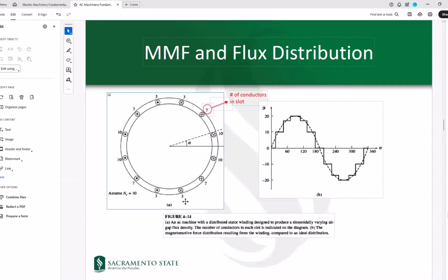But that is not as simple as that. You really have to have a specific setup to make that pattern in a sinusoidal way, if that makes sense. So this is just something to note. So this was only for phase A, and now for phases B and C, you can imagine that you would need to have some phase shift, with some extra slots in here belonging to the other two phases in the same specific manner with some phase shift, if that makes sense.